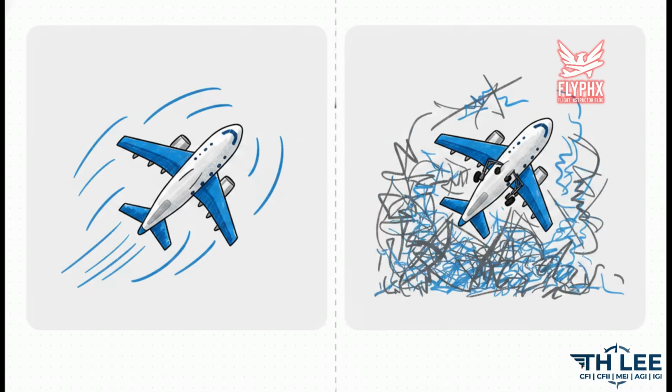Okay, we're airborne. Now let's talk climb performance. If you're lucky enough to be flying a complex, retractable gear aircraft, the difference between your gear up and gear down climb charts comes down to one massive, undeniable factor: drag. Leaving that gear down creates a huge physical drag penalty. Aerodynamically speaking, as drag goes up, your available thrust physically goes down compared to what's required. A clean, gear-up climb eliminates that penalty completely, maximizing your thrust so you climb faster and much safer.